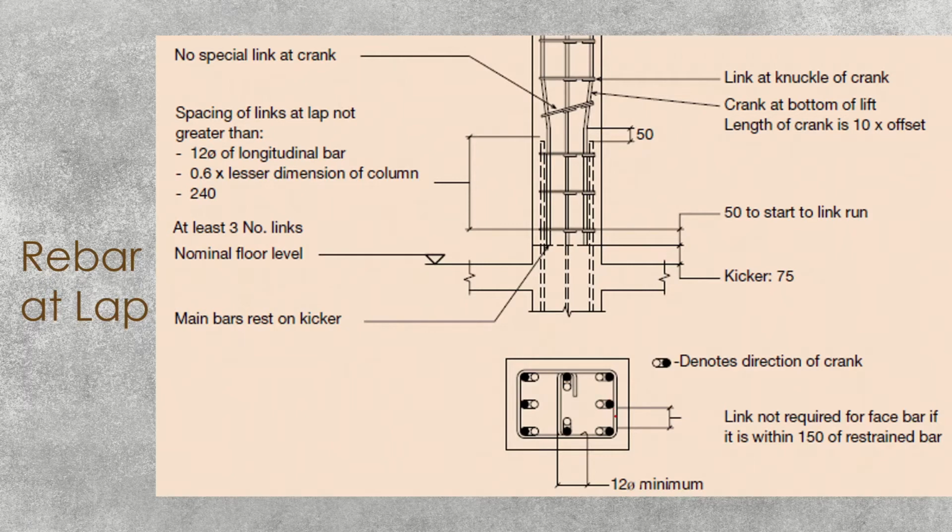As I mentioned previously, if you have a sufficient gap here, you can have the reinforcement lapped here also, and if that satisfies the design requirements, you can put the side lap. If you can't reach that, you have to provide cranking like this, because if you have a link like this, you can't put the side lapping, and then you have to crank this bar.